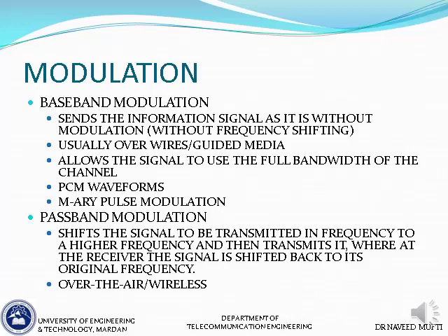Whenever we do that, that is basically passband modulation, and that is what happens in over-the-air or wireless communication, because that is when we shift to higher frequencies. Take your mobile signal: your audio signal is up to 4 kilohertz, but when it is sent to the BTS, it is at 900 megahertz or 1800 megahertz or 2100 megahertz. So it has been modulated, and that modulation is passband modulation.